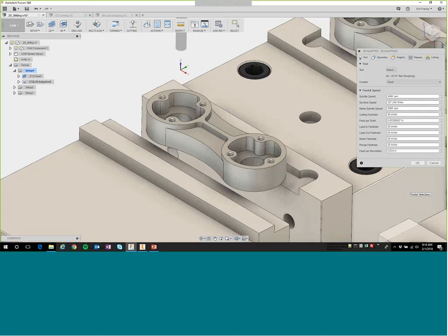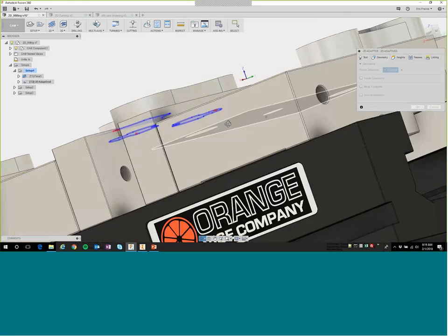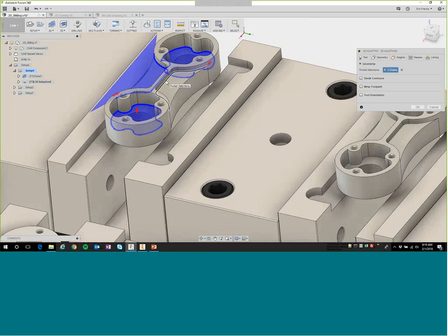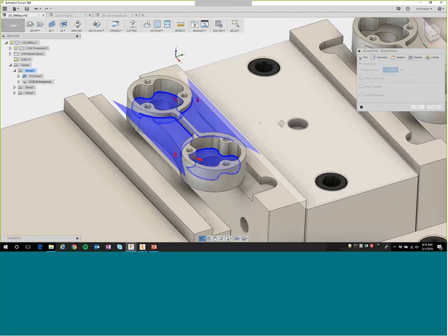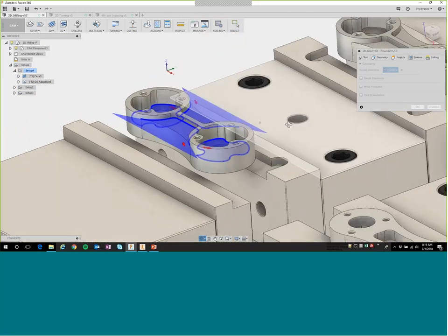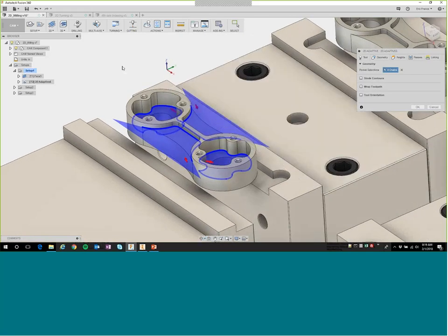The benefit of this tool is that it's going to scallop, basically taking the same size cuts every single time as it's going into the material, so that we're not burying the tool in the material and modulating the load on the tool, which tends to shorten our tool life and cause additional wear and could even cause problems in the part itself, and how the part's being machined.